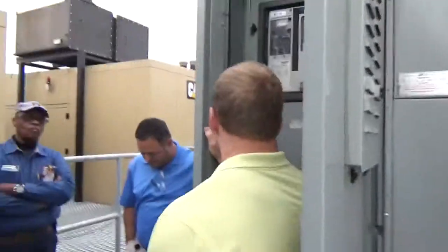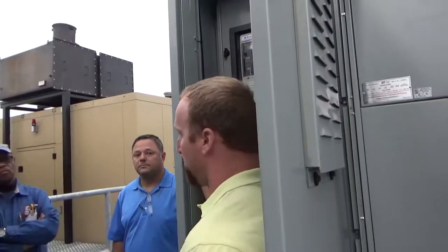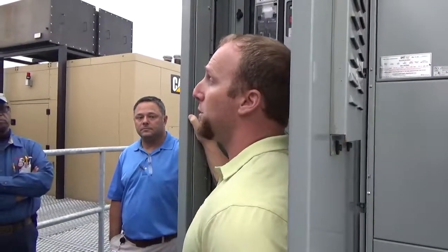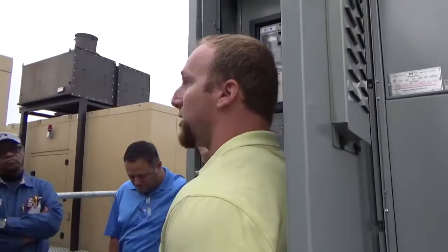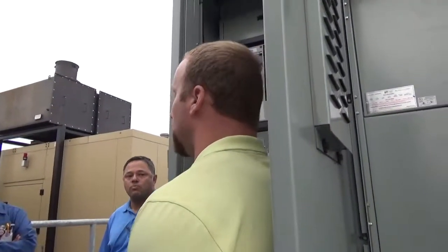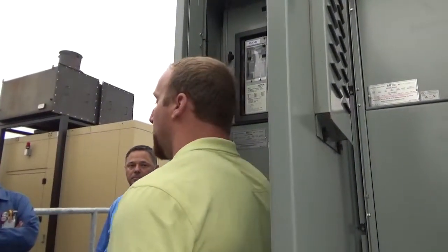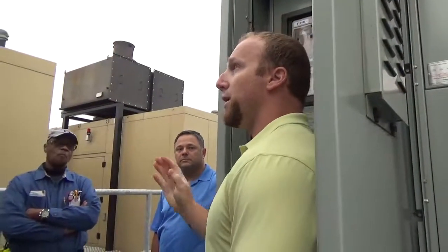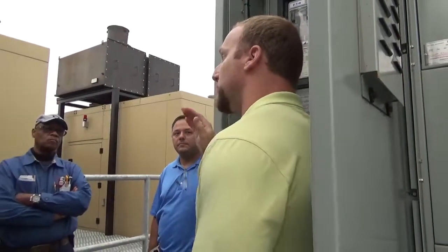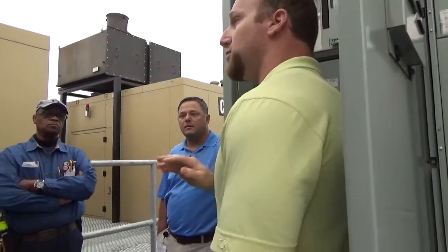Okay, so now that we got the gen demand out of the way, I'll go ahead and explain another feature which you guys won't be using, but it's good to know that you have it. Another one's called load shed. Load shed is a feature if you start overloading the generators. That's only going to come into play when you have both generators on the bus. So if you eventually start adding a bunch of stuff to the hospital and you are going to exceed 2 megs, then you're going to have certain load shed conditions where at a certain percentage of rated kW on the bus, it's going to start dropping loads when you have 2 gens online.